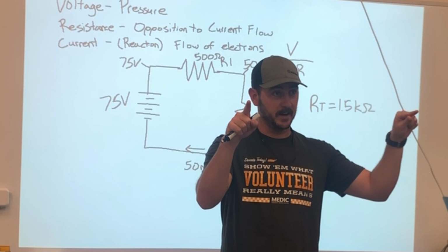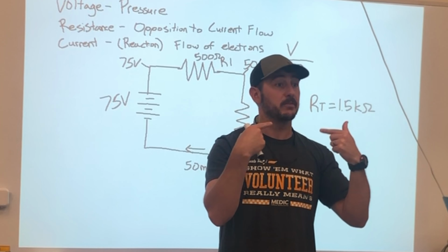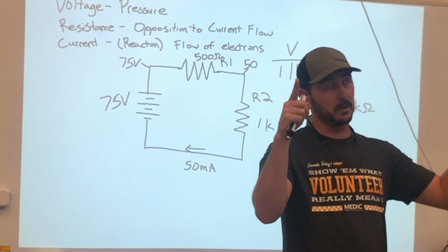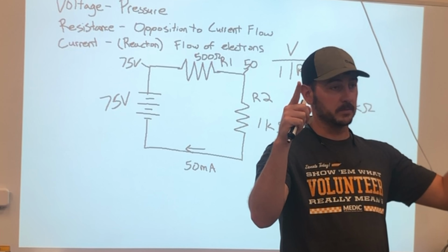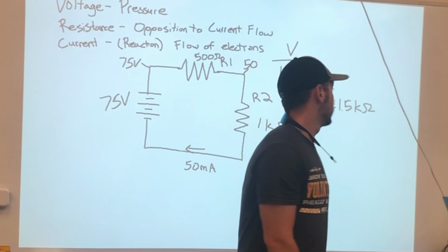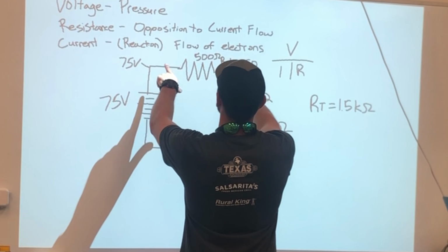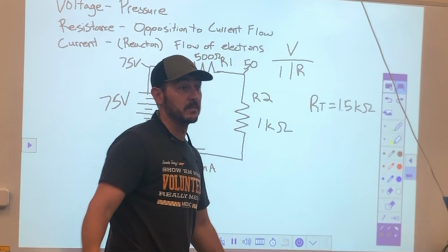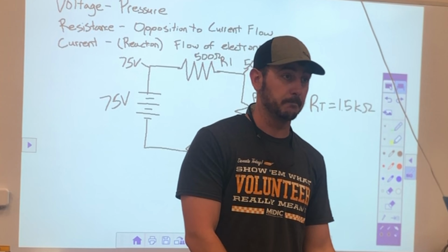How much voltage do I got here? And then it tells you the difference. So if this one reads 10 and this one reads 30, what's my meter gonna read? 20, it reads the difference, right? So I measure across this resistor, what's it gonna tell me? 25, the voltage drop of the resistor, okay?